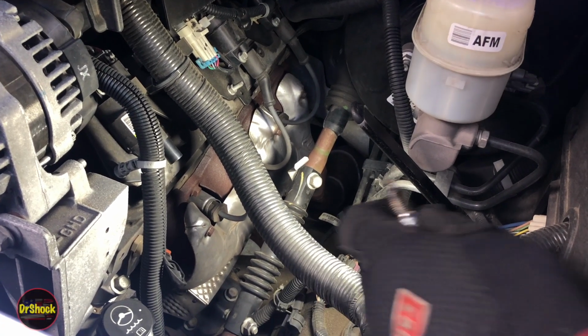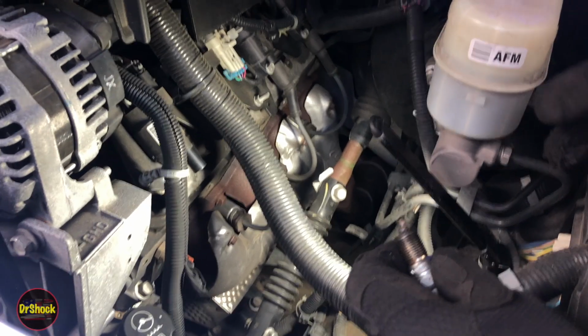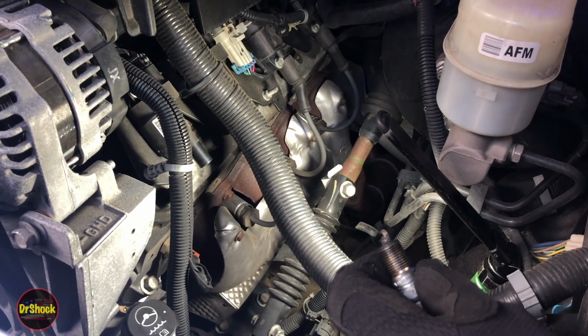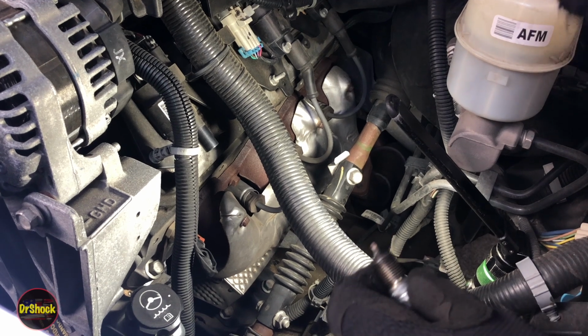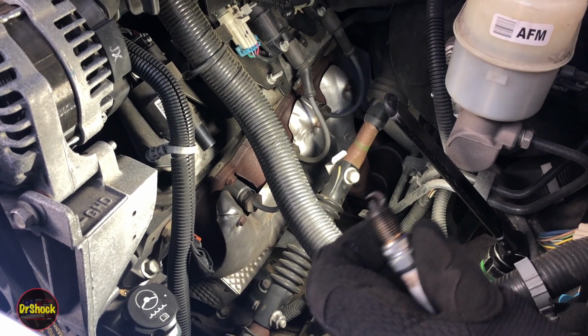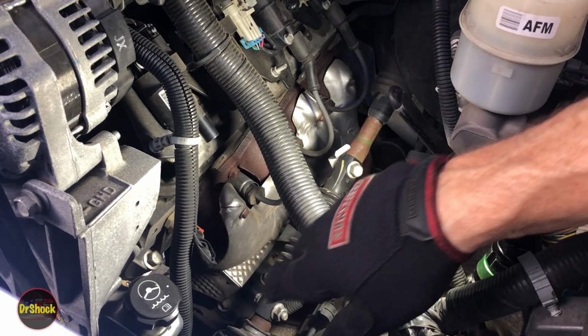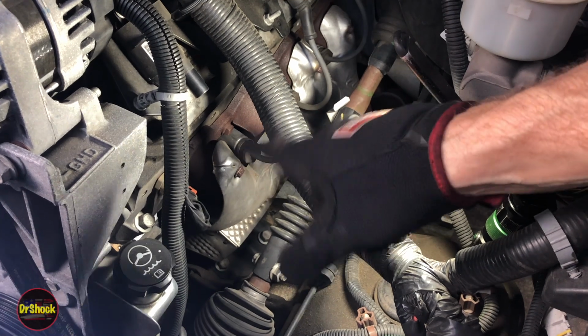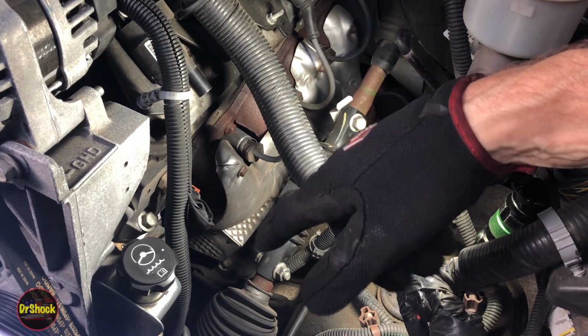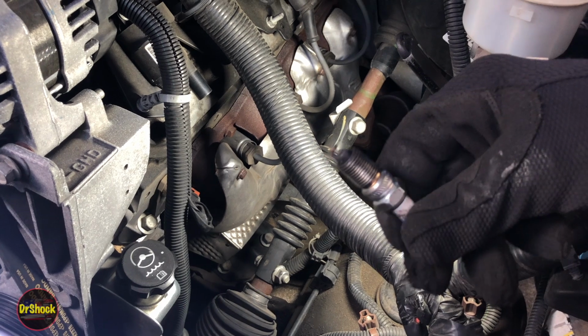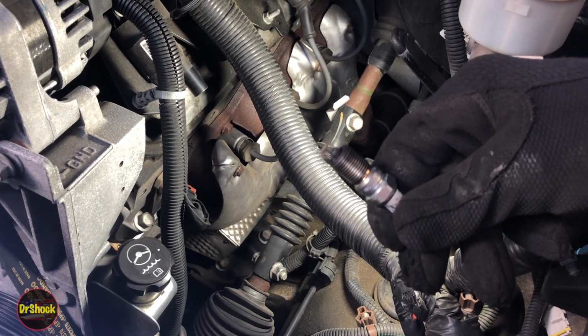But since we've got this repeating pretty easily, I've stopped the engine and restarted it, and it keeps racking up these misfires. So it'll be a pretty straightforward test. What you could do is we could swap this plug with the number 3 if we didn't have this spare one. Since we got the spare one, and I don't like the condition of this one in the first place, we're just going to put a new one in there and see what happens.